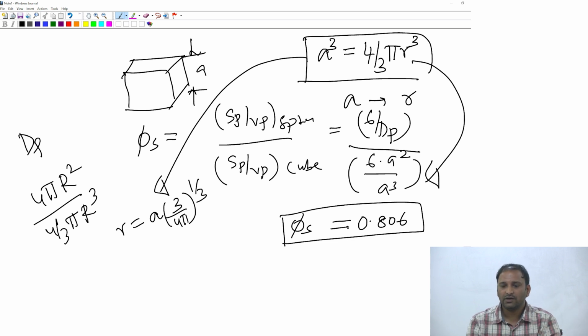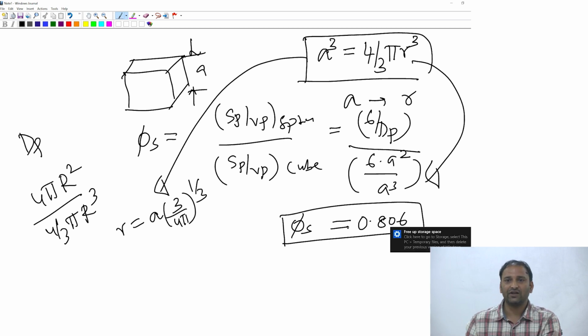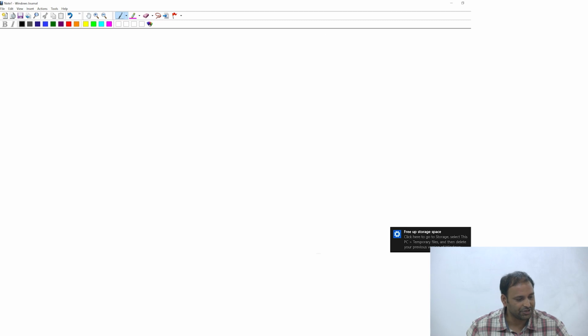So this sphericity tells you how to consider the shape effect. You will look at a lot of expressions developed for spherical particles, but the deviation from the spherical shape is accounted for by incorporating sphericity into the calculations. So in that context, this is an important parameter that you will come across in some calculations.